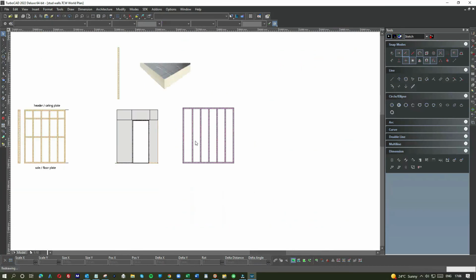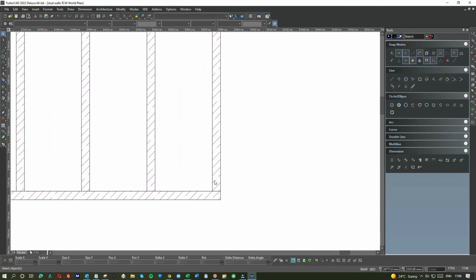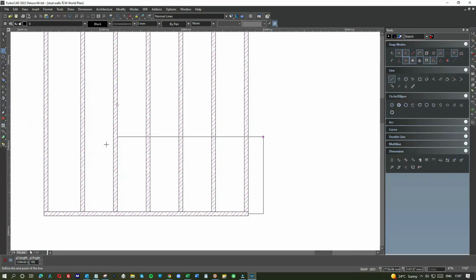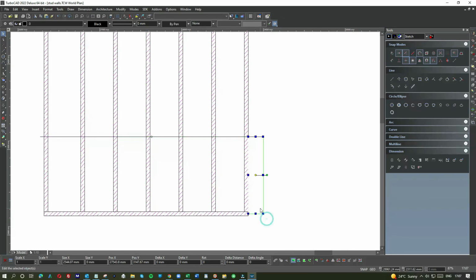Now it's noggins. This time we're going to use 300 again. 6x3, 1800. So if I do, that's the quick simple way, tab 18. No, that's wrong. That should be 900, because it's 900, and that's all the way along 900. So we're not doing any door or window on this one.